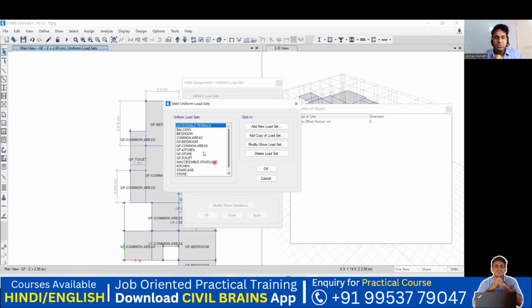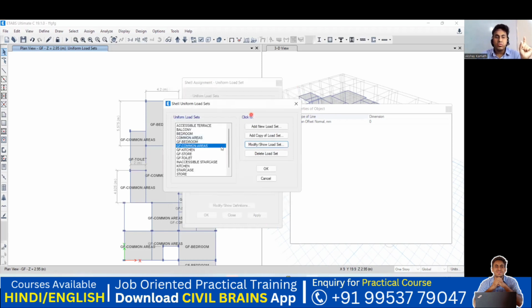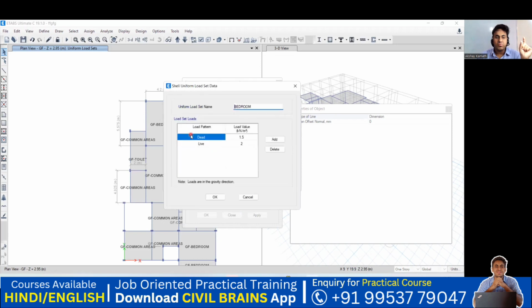Where is that common area? Okay, GF common areas. Yeah, modify. Okay, they have taken dead load. Dead load in the sense of self weight of the material. It is 0.3 and your live load is 0.6. So I'm supposed to apply this load over there. Otherwise, I'll go with a different load. Let me go with a bedroom. Can you see the dead load we have taken is 1.5, and in the bedroom, if you remember, the live load is 2 kilonewton per square meter. This load we need to input here.